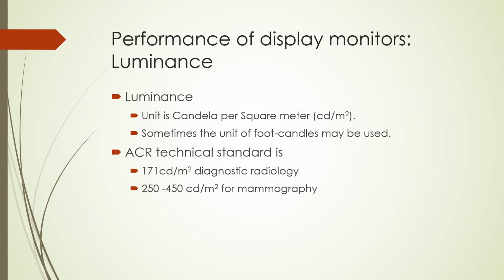The foot candle is defined as the amount of illumination the inside surface of a 1-foot radius sphere would be receiving if there were a uniform point source of 1 candela in the center of the sphere. The candela itself is an old unit from the time candles were used for illumination. In order to be able to work by candlelight, it was determined that you needed about 70 to 90 foot candles of illumination, which means you need a light from between 70 to 90 candles on the work surface.